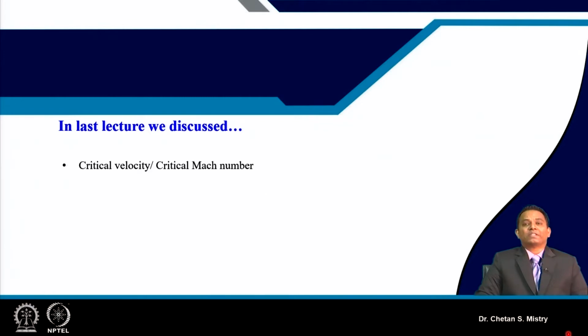Yesterday we were also discussing two different design approaches. First, what we call a sizing problem, and second, what we have defined as a rating problem. Sizing, in the sense that we are talking about a new design of an engine or a new design of the compressor stage for an industrial application. Under that condition, we know our input parameters, we know what pressure rise we are expecting, maybe we can calculate the rotational speed, and all those parameters are known to us.